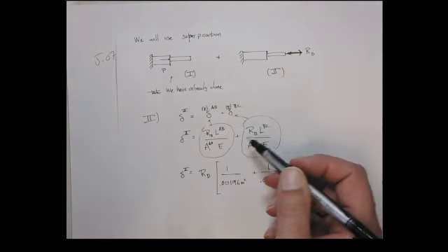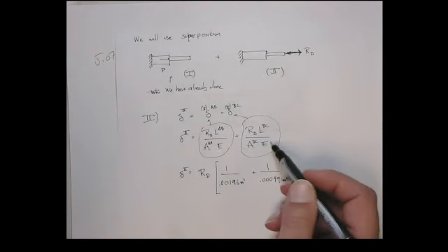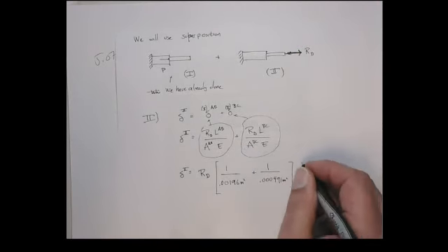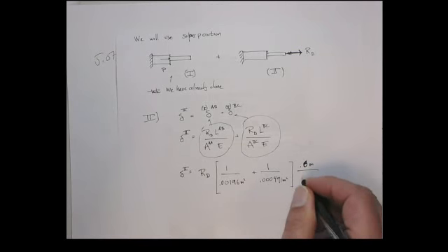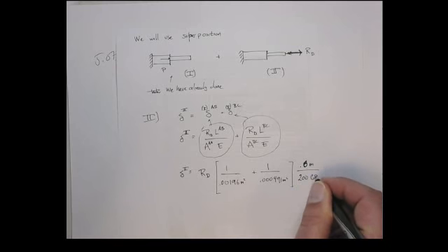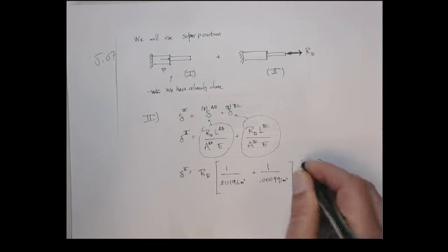The L actually happen to be the same in this problem. They're both 600, not normally. And the Young's modulus is the same. So we can just take the 0.6 meters over Young's modulus, which is the 200 GPa. All right?